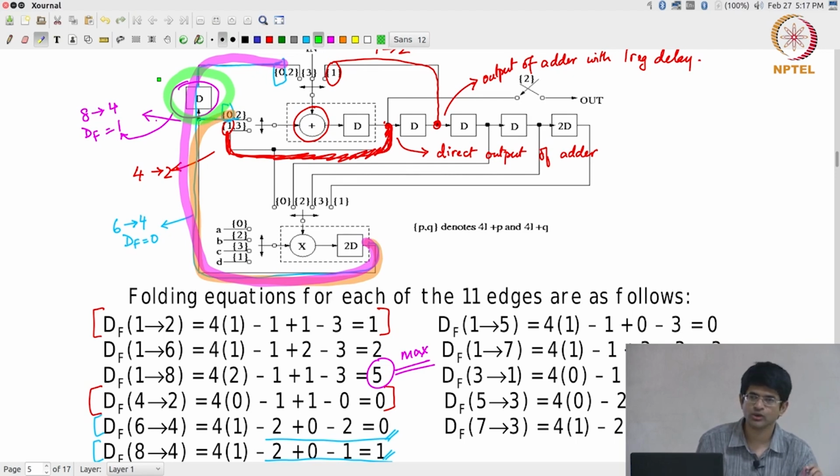Now the fact that I could use that particular register in order to do both of those was not entirely obvious from the original design, okay, that I could share this particular register. In particular, if I had chosen to give this multiplier input to the other input of the adder at phase 2, right, I won't be able to share this register.